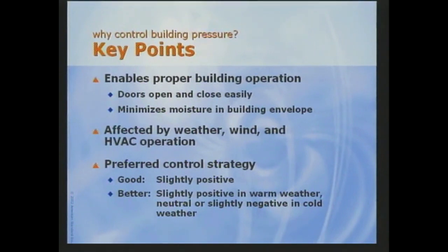And the driving forces for changing pressure in the building include the weather, wind, and the mechanical system. And while we can't control the weather or wind, prevailing conditions should be taken into account by the designer. These driving forces may or may not be critical in your building, but even a one-story building experiences stack effect. It's just not real important because the pressure differences are so very small. Finally, when it's hot and humid outdoors, the building should be slightly positive. When it's cold and dry, the building should be neutral, or maybe even slightly negative in some climates.